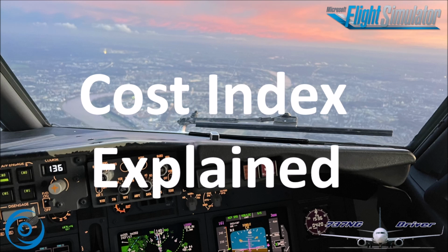So, how big is that change actually going to be then on our actual flight? Let's take the average flight of approximately 1 hour and 20. If we change from a cost index of around 10 to a cost index of 100, then we would be using typically around 200 to 300 kilograms more fuel, and it would give us a time saving in the region of approximately 8 minutes.